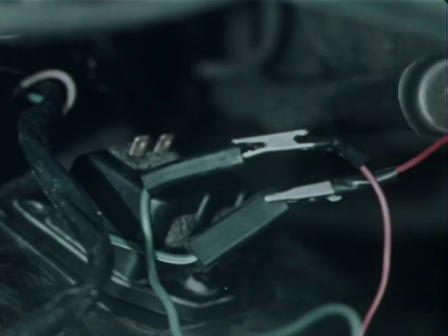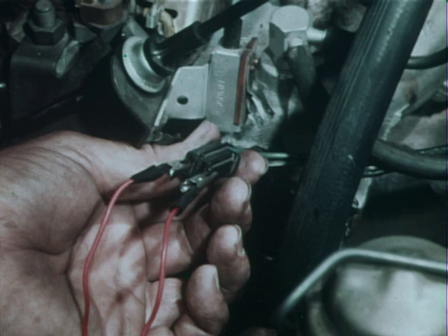He attaches a jumper wire across the terminals of the thermostatic switch connector. If the clutch engages, the malfunction is in the thermostatic switch. Since the clutch does not engage, the technician continues his diagnosis. Keep in mind that on C and K series light trucks, the test procedure would move from the thermostatic switch to the compressor clutch switch at the control panel.